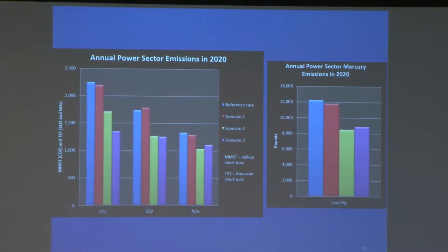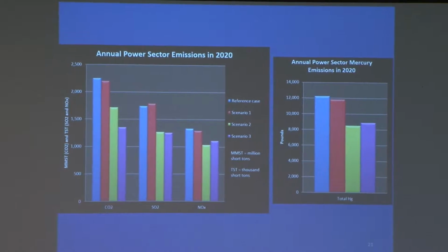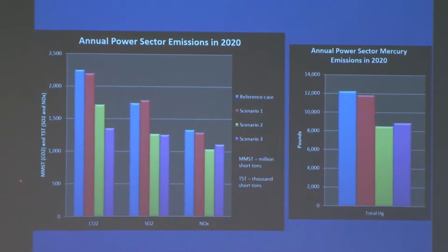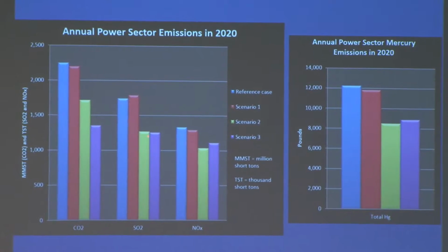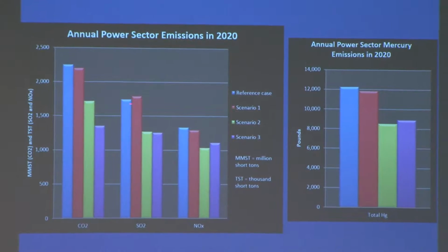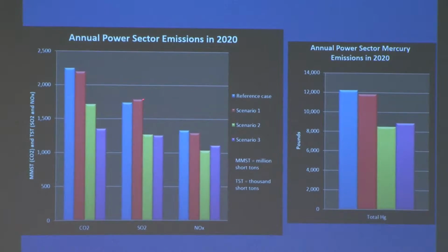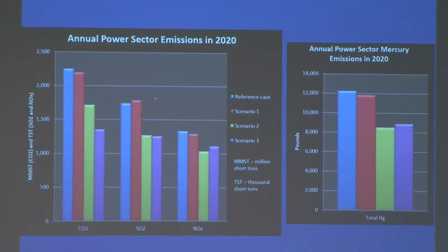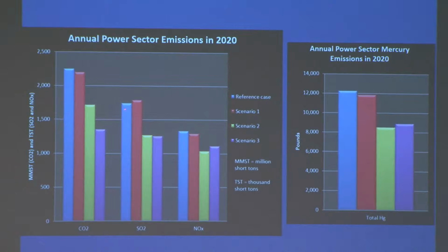So in terms of how this translates to projected emissions, these are shown here. And you can see that for coal with the power sector scenario, with the improved heat rate, there's a slight increase in sulfur dioxide emissions here. And that's because if we improve the energy efficiency of these old units, they move up in the dispatch list and they burn more high sulfur coal. So it's not very large, but it's reflective of a phenomenon called emission rebound.